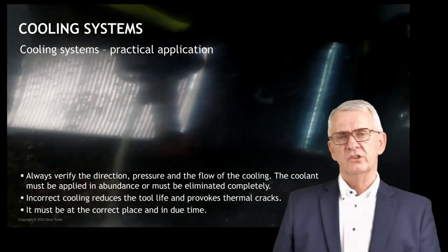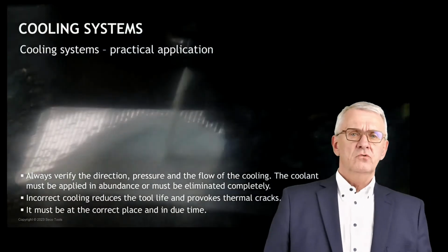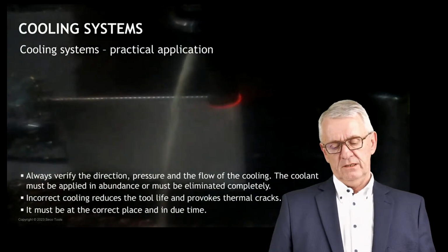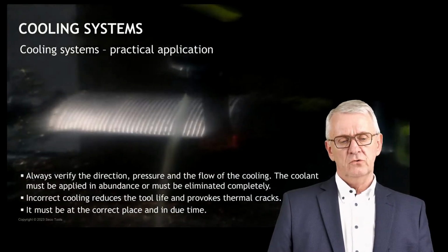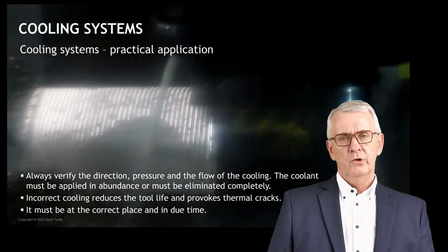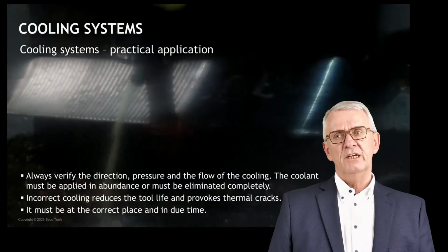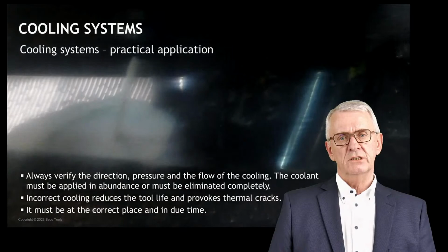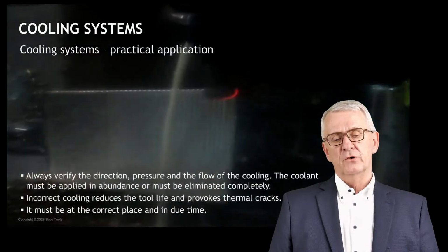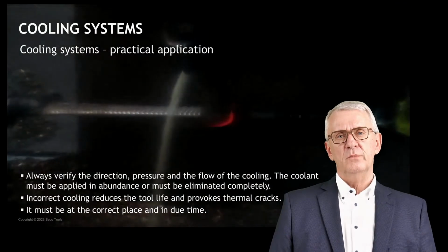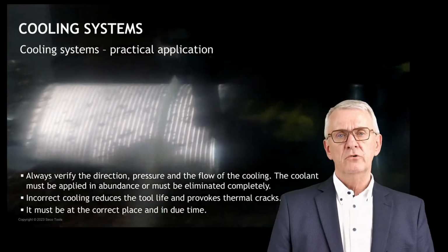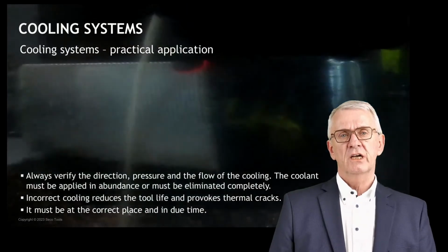What I try to say here is use cooling. There's one discussion: should I use cooling? Yes, no. But anyway, if you decide to use cooling, do it correctly. I mean, do it where the cooling is needed. If you go for emulsion cooling, there should be abundant fluid on the cooling process.